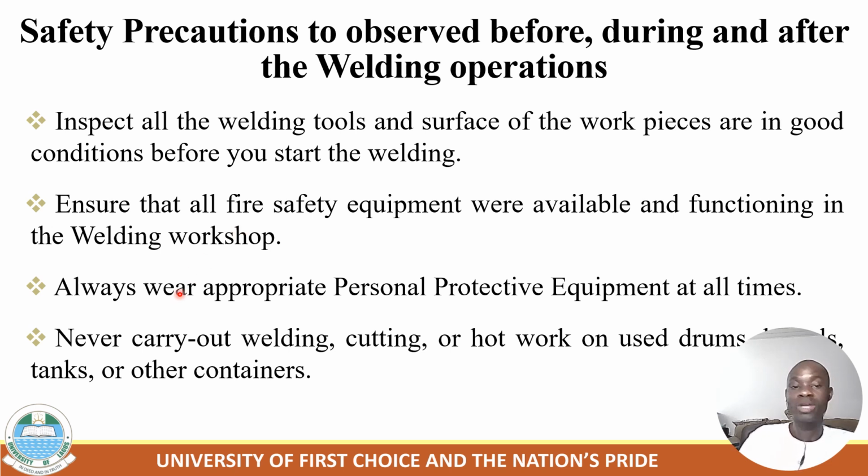And also always wear appropriate personal protective equipment at all times before doing the exercises. And never carry out welding or cutting on a used drum, tank, or other container, to avoid explosion.